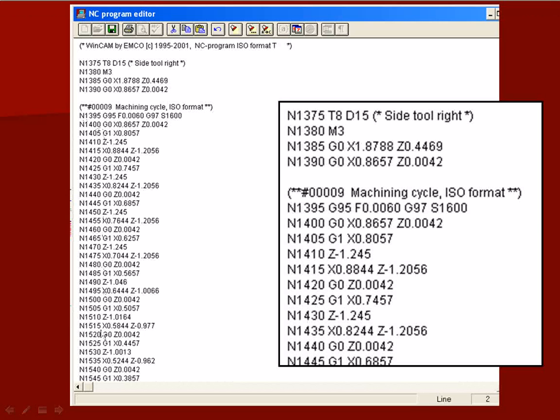Let's say this is your G code, and this is an example from the CNC lathe. If you look closely here, we have X and Z, X, Z, X, Z. There are only 2 axes, because your X in the lathe refers to left and right movement, and your Z is forward and back movement, or how deep you want to go into the piece. There's no Y axis in this case, as there is with the CNC mill.